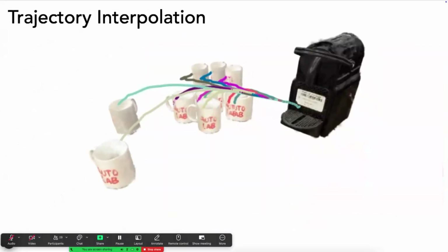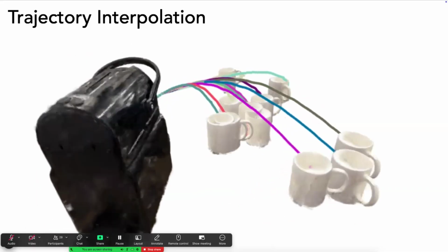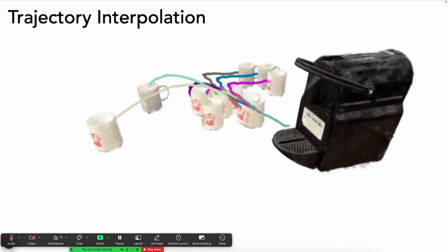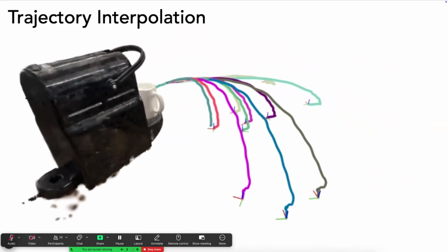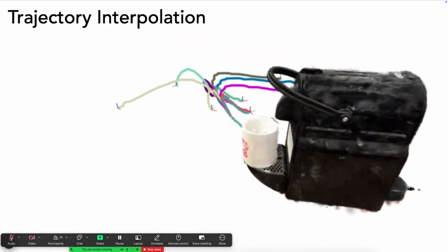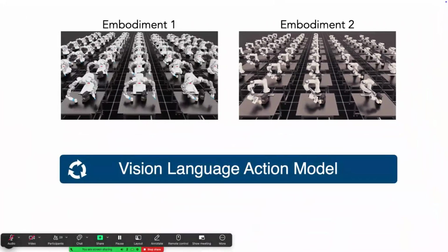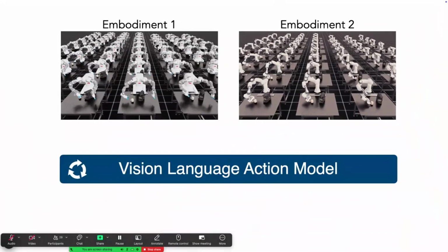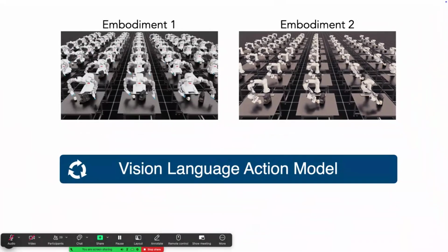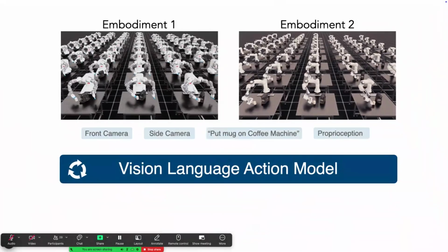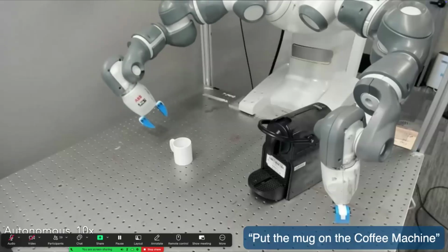etc. And for each of those, generating a family of trajectories for the different inputs. You've only given it one demonstration, but it's synthesizing and rendering many different trajectories. And then basically you can use that to train it for your robot. So you have maybe a pre-trained VLA that may work for different embodiments, but you can plug that in for your embodiment and it will generate motions like this.